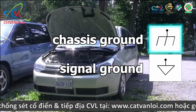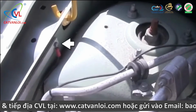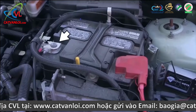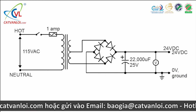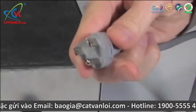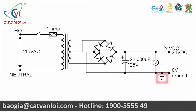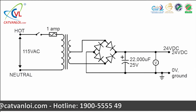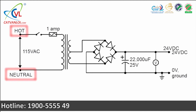This one means chassis ground, such as the chassis of a car, basically a continuous piece of metal that many things in the car are connected to, including battery negative. Sometimes though, the ground symbol does actually refer to connecting to earth ground. This is the schematic for this power supply. One that you plug into a wall with a plug that has a ground prong. In this case, the symbol is saying to connect to that ground prong. Though I guess the only hint is that these points are labeled as hot and neutral, the names for the other two prongs in the plug.